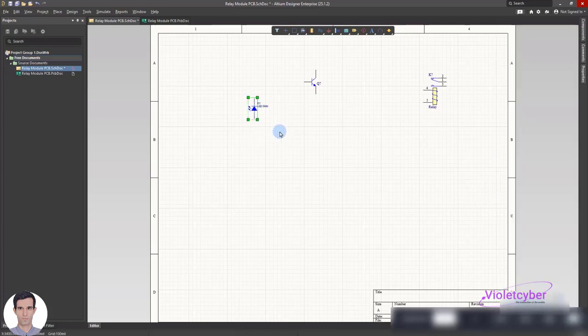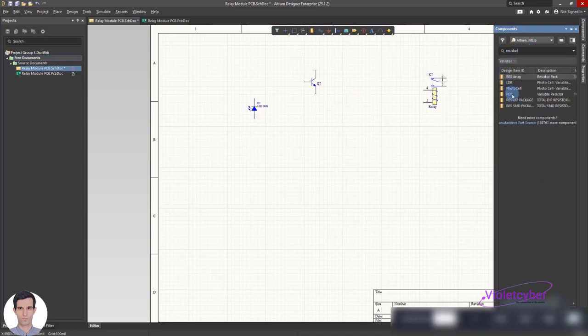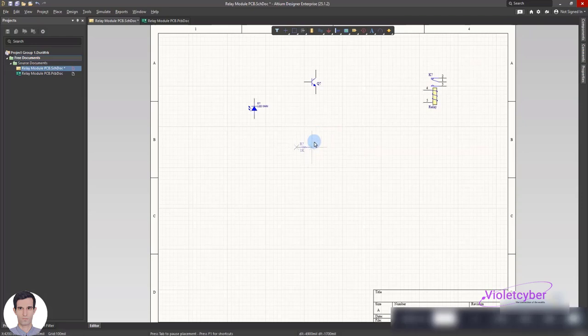And then we'll go to the resistor, which when you select it, as you can see here, brings both DIP and SMD. But we're working on the circuit right now because it's DIP. Of course, if you want, you can choose SMD. It doesn't matter. See, when I select the resistor and move the mouse, it brings the resistor onto the screen like this. If I click once, it leaves the resistor and waits again for me to place the resistor somewhere else, meaning it's set.